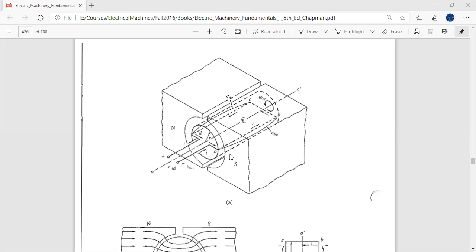And the key thing to note is the permanent magnet being used as the main field in this case. So the main field is on the stator, and there's a single loop of wire which is attached to some axle, so that that single loop of wire could rotate.